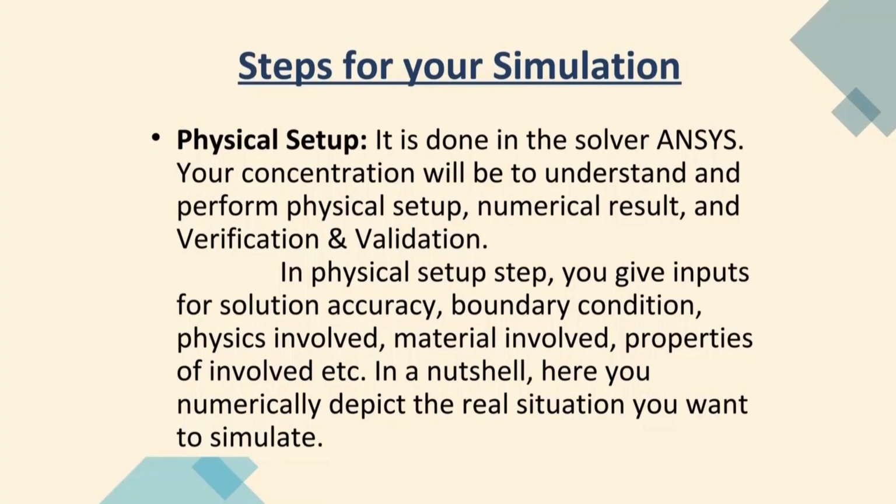Now, the physical setup. This is another important thing. Fluent already gives some advice on which type of model, like natural convection, what kind of solver, and what kind of discretization you need to use. So they already give some idea, or you can do it yourself, do different testing. But remember, in CFD, good results depend on your experience. So do it again and again, and you will get experience. What is the problem? Where is the problem? Then you can identify it by yourself.